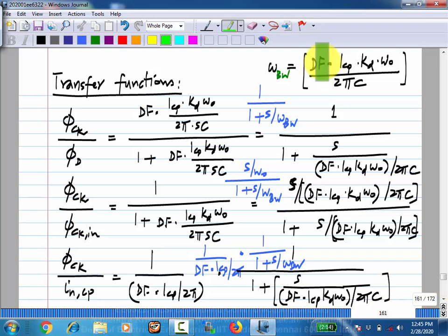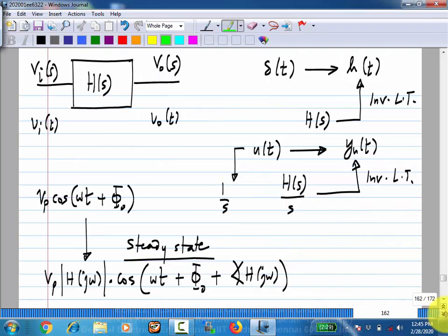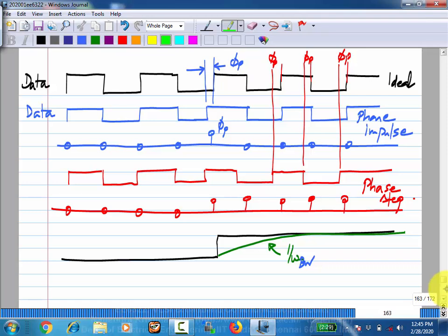And one other thing is the transition density factor. You can see, for random data this will be half. You can kind of consider it as fixed. But if you do have cases where you expect very few transitions, right? Then you have a problem everywhere. First of all, the bandwidth will be lower because it takes more cycles to correct it, and then also noise becomes higher. Okay, again the whole thing happens because you don't have enough information to go on correcting the phase. Is it okay? Fine.